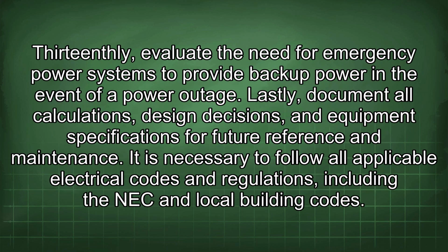13thly, evaluate the need for emergency power systems to provide backup power in the event of a power outage. Lastly, document all calculations, design decisions, and equipment specifications for future reference and maintenance.